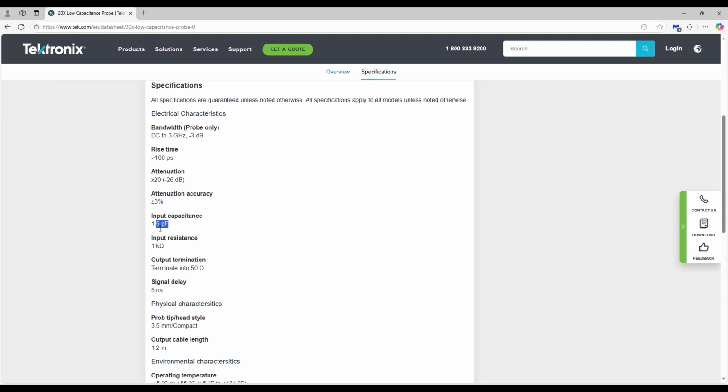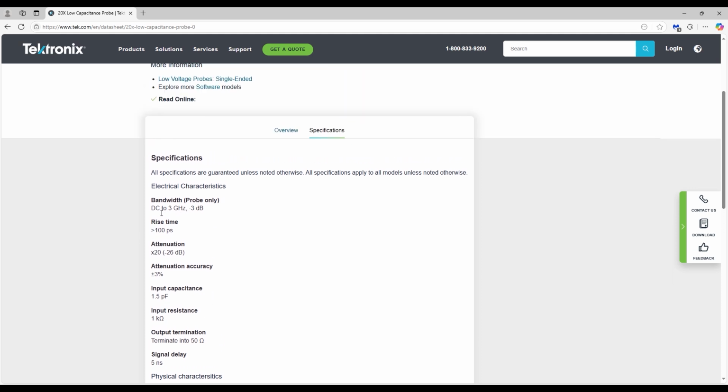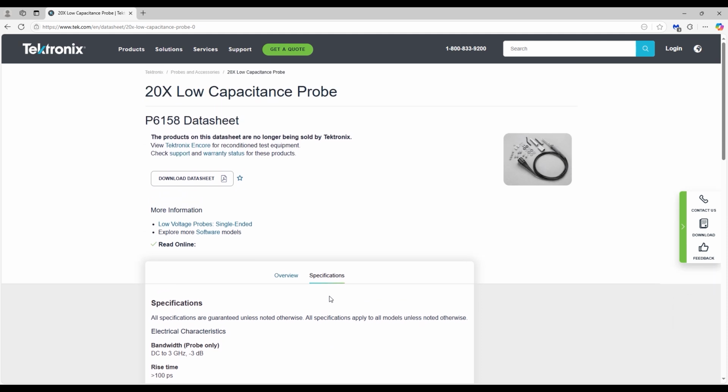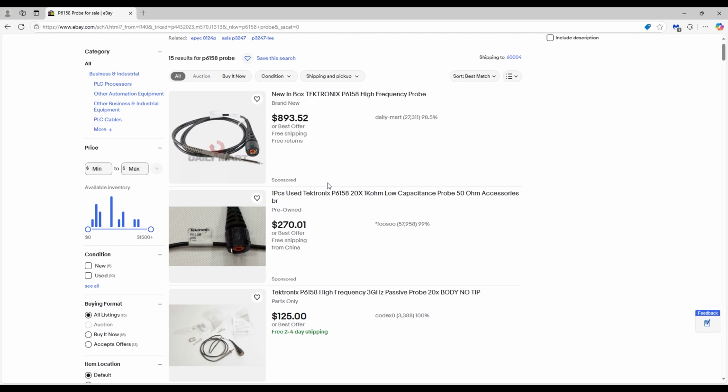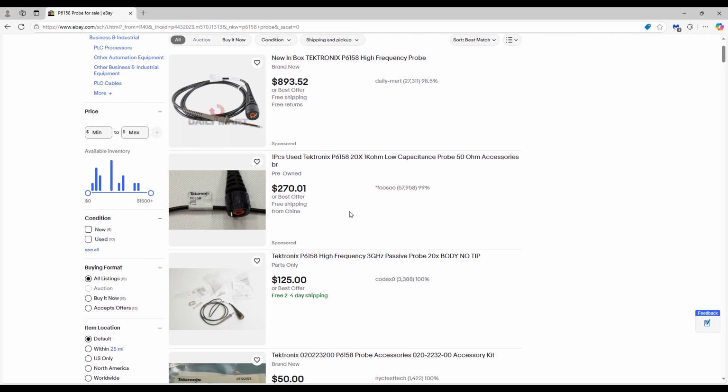Now that's critical for AC performance. Higher parasitic capacitance will limit the maximum useful frequency. It does pass DC though, so you'd need to insert a blocking capacitor between it and your 50 ohm equipment, which is right back to adding high-pass filtering that might be undesirable. Unfortunately, it looks like Tektronix stopped making it a few years ago. You can pick up a used one, of course, but even used ones still run for several $100.